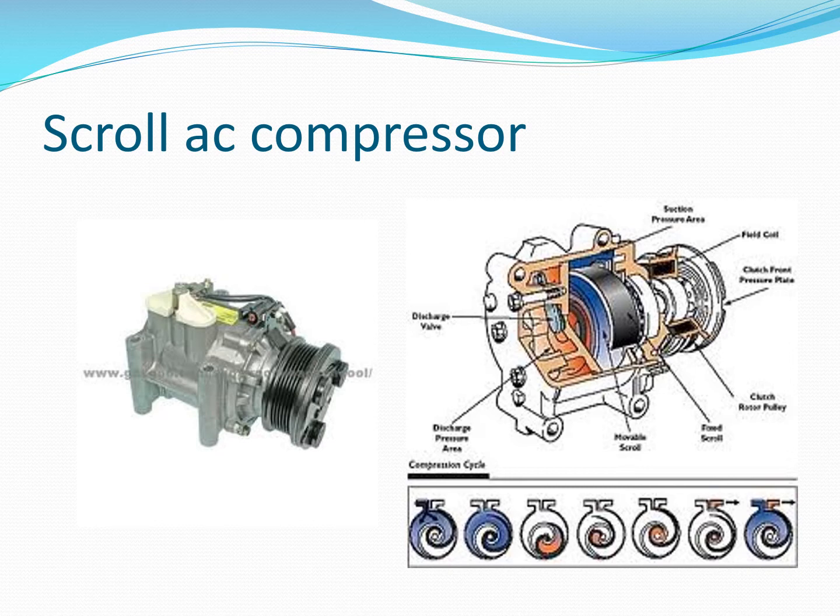But because the device that's actually compressing the refrigerant is not reciprocating and really not rotating either, the scrolls on these compressors are a high failure rate item. And when they fail, the compressor fails in a very large way. The scrolls break. I would encourage you to Google scroll AC compressor and Google video and watch some of the videos on this.